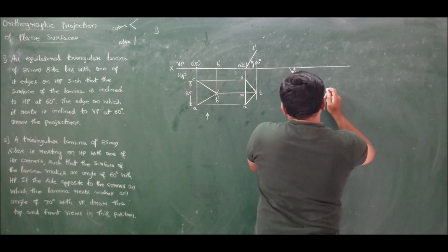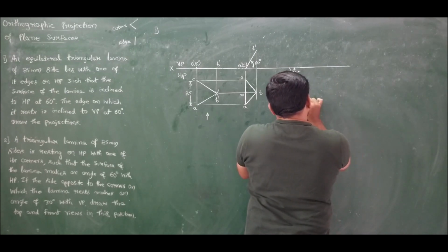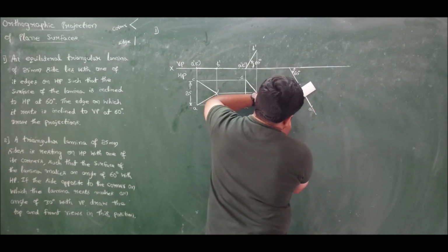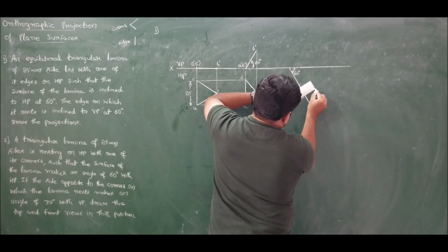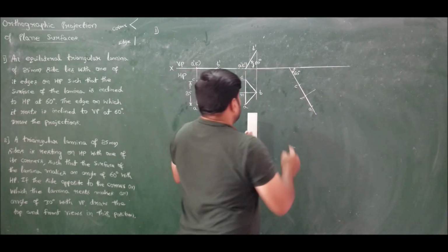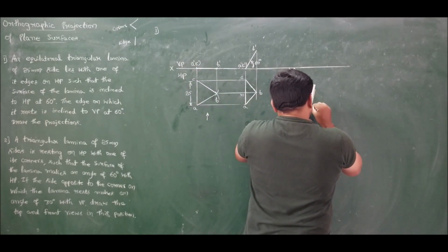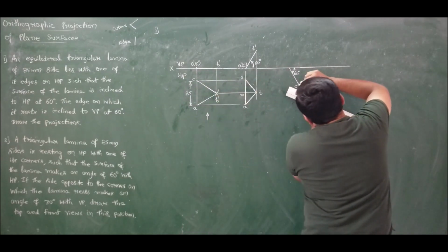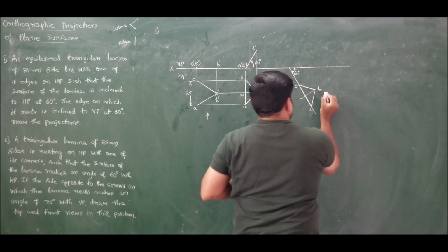So exactly at center you mark the exact center, that is M. From M you show 12 millimeters, a small line which is very thin, because that is for our construction. Now I have placed it here. Locate point B, that is corner B. So I got corner B.